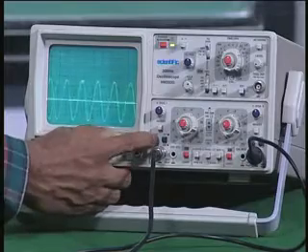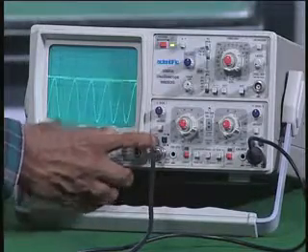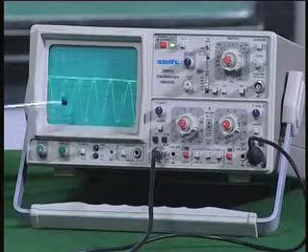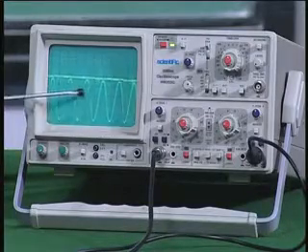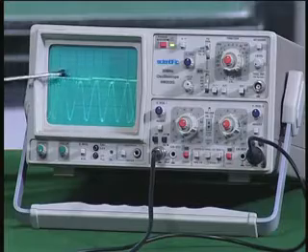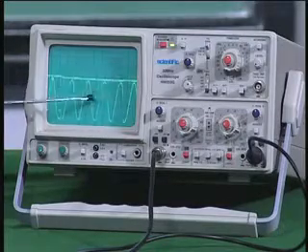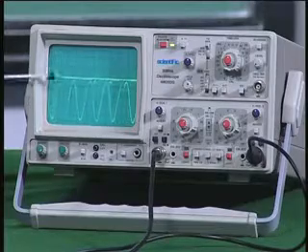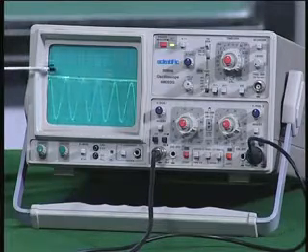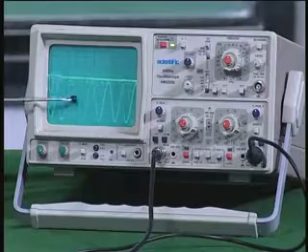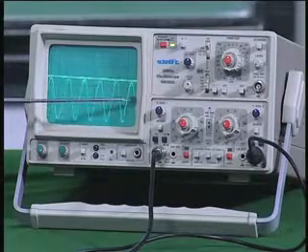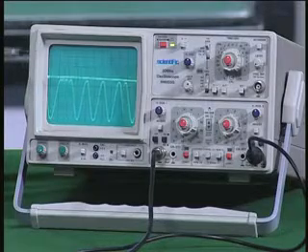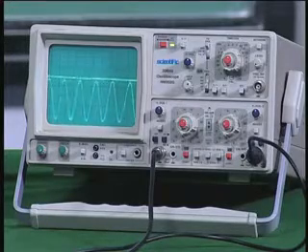So it is indeed detecting the peak. So instead of using a multimeter, I wanted to show you by using the DC coupling here that it goes from the 0 line to the peak value here, and this is the DC output that I get across the capacitor. So the output is a DC, therefore it looks like a straight line, but it is shifted with reference to the 0 line up to the peak value, and therefore it is indeed a peak detector. I hope you understand that point.